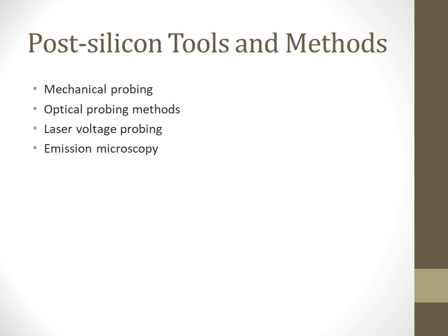This is usually essential to validate that the failure is completely understood and sometimes to also check out a possible fix before actually implementing it within the design. The ability to check out a fix before committing it to silicon is critically important as revising silicon can be very expensive and time consuming, which can affect overall product schedule adversely. There are a number of tools which can be used to probe actual signals on a device to verify the root cause of a failure.